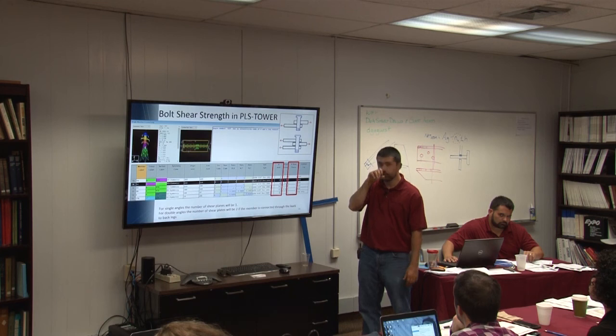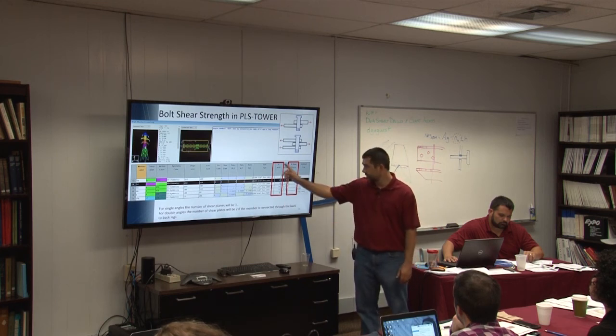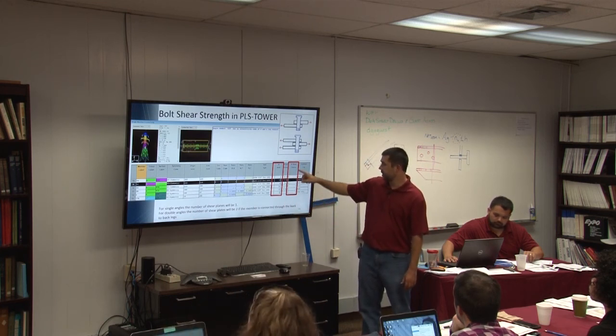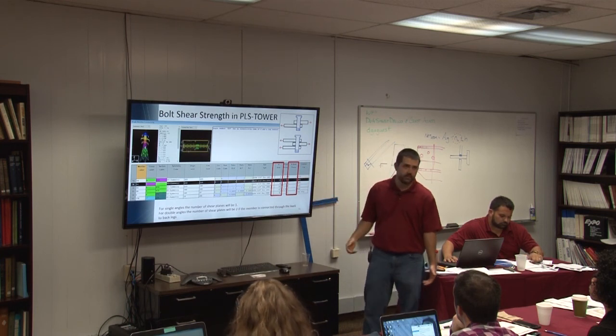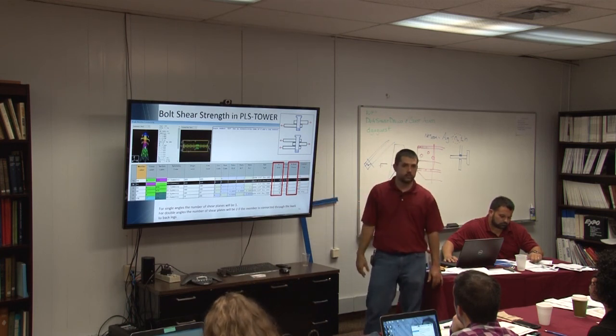So this one, again, is pretty simple to calculate. You don't need to do anything special. Just get the number of bolts right. And like I said, if you get something that you have bolt shear problems, make sure your number of shear planes are right.